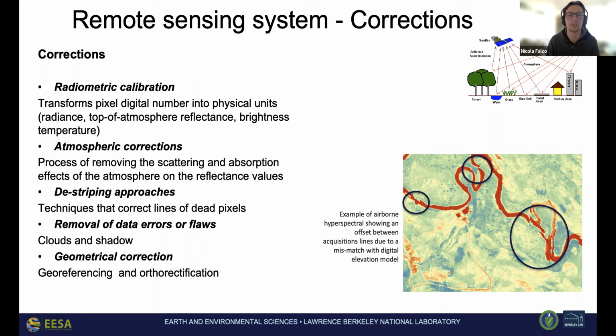There's some areas where it breaks down, and there are shifts here and there, right? So going back and rerunning orthorectification, looking at whether the DEM has issues and so on, this is, you know, a very intensive process to really have final, high quality data.